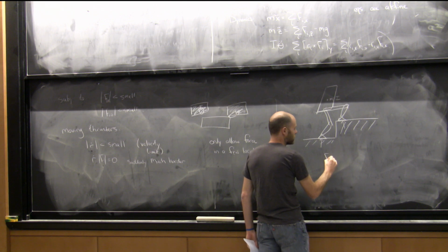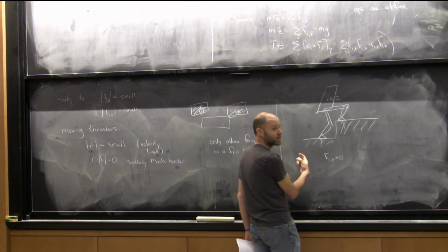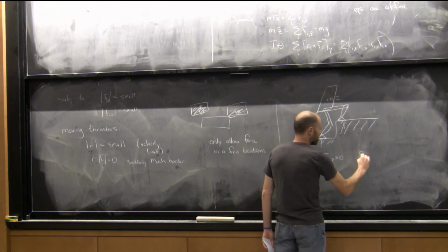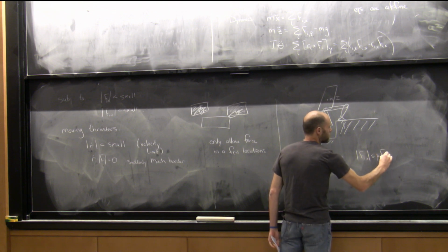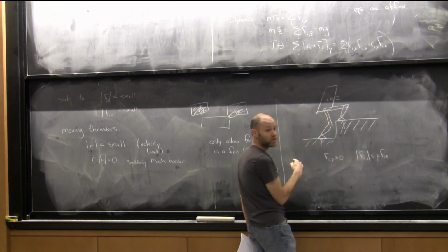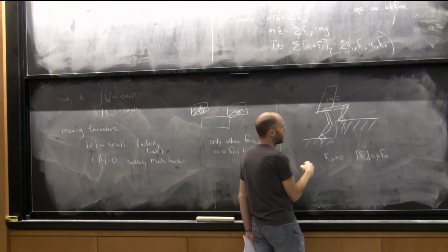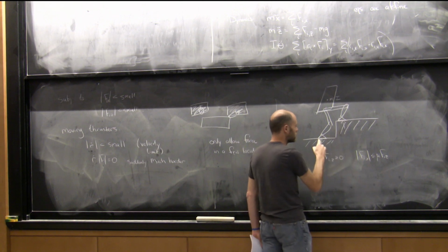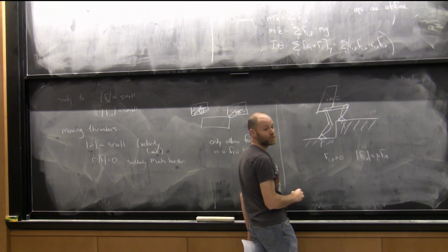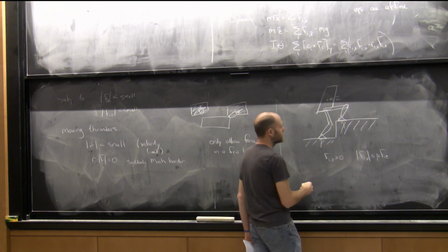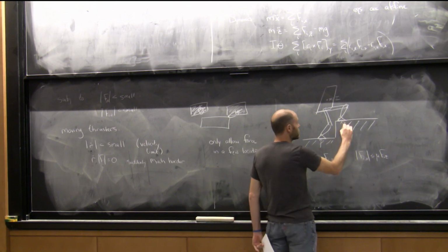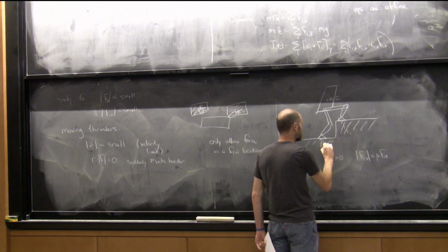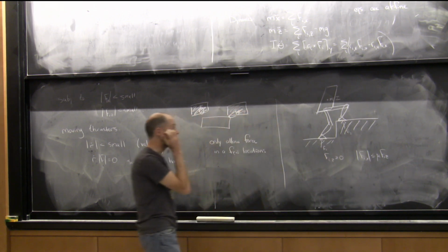For instance, I say that Fi of z has got to be greater than or equal to 0. So there's a constraint on this, right? And then Fi of x is going to be less than Fi of z. They're linear constraints on the friction, okay? And they can only be producing force when the foot's not moving. That's the simple case, until we're doing ice skating or something. Okay, that's basically the problem that we have to deal with in a more complicated robot. Okay, and that's the most relevant problem.